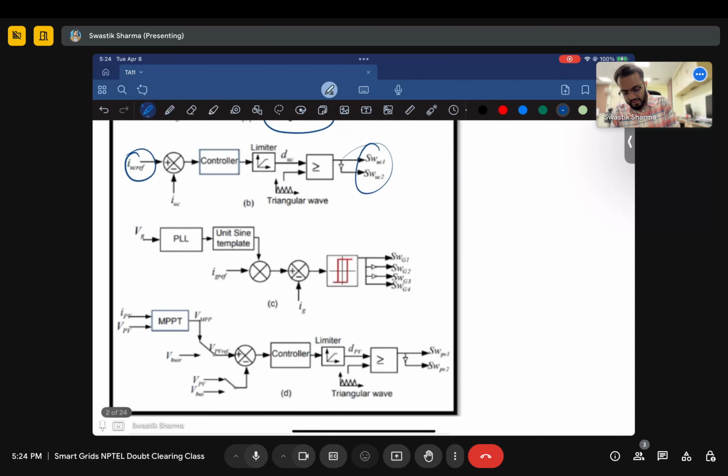Next you have the grid. The grid is connected to a phase lock loop, and we have talked about what this phase lock loop is. It is used to ensure that the reference signal that we have received matches closely with how the voltage phases are, right? If the reference that we are generating moves out of phase, then that means our signal will no longer be valid, right? And that is what is happening.